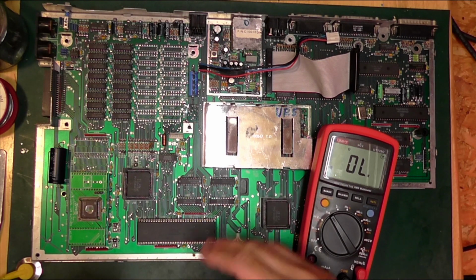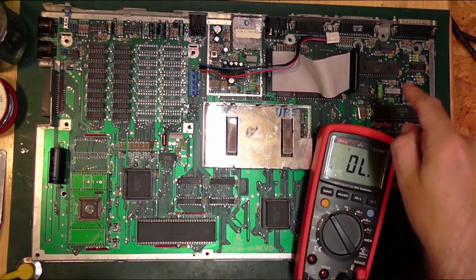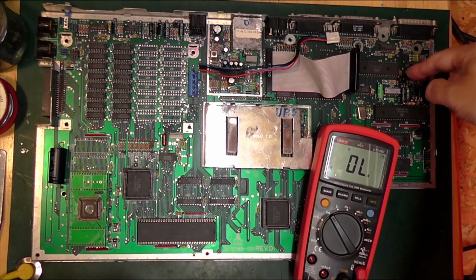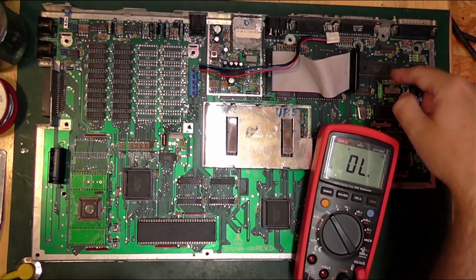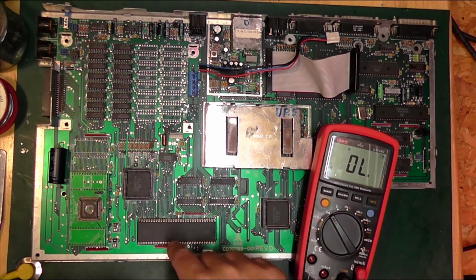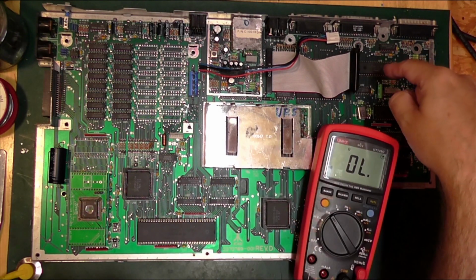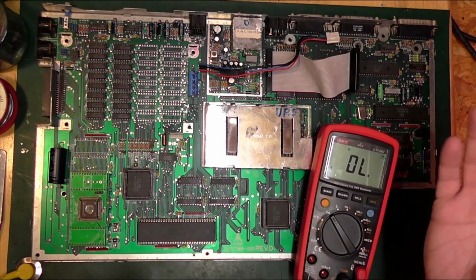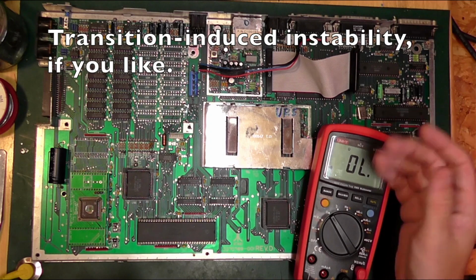And if you've got something driving it over here and you're listening for it over here, or vice versa, there's the chip. So over here we've got the Yamaha sound chip. If we've got that doing something, or that listening, and the processor here driving, that's a long way for that line to stretch, and you're going to get ringing and bouncing and basically noise on your line.